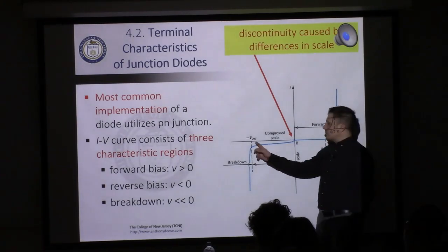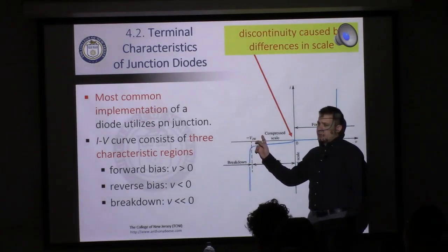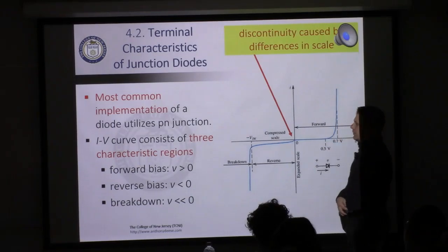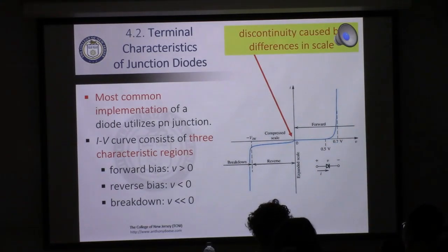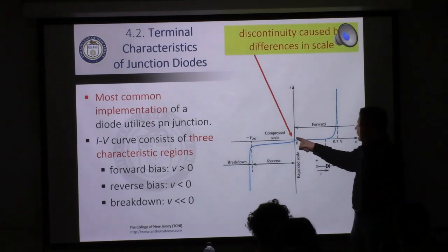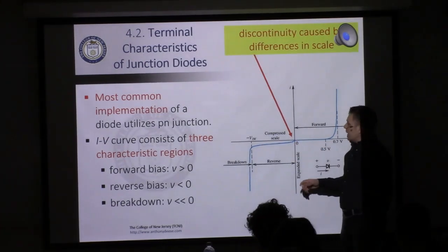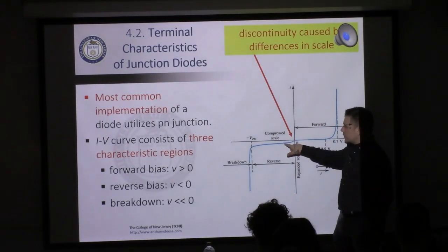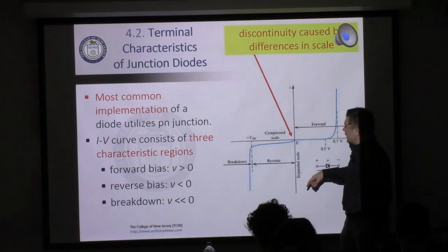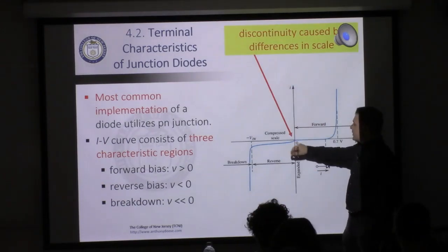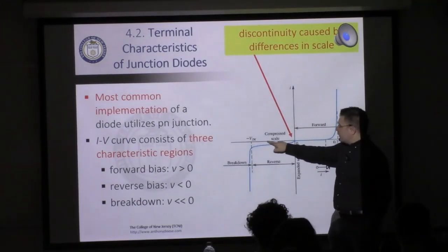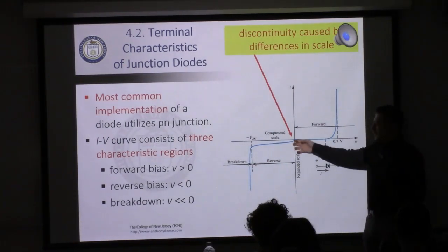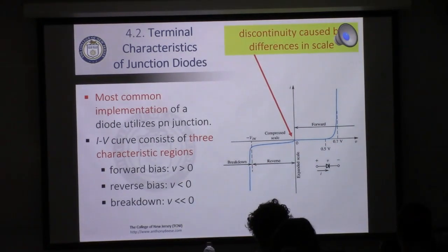Normally we call this voltage here the Zener knee voltage, denoted by V sub Zk. One thing I will point out, the reason why there's a weird bump here is because they changed the scale going from the right-hand side to the left-hand side because they wanted to show there was some reverse current. But in reality, if these were on the same scale, it would just look like that. I feel like this is actually more confusing the way that they drew it than it would be otherwise.